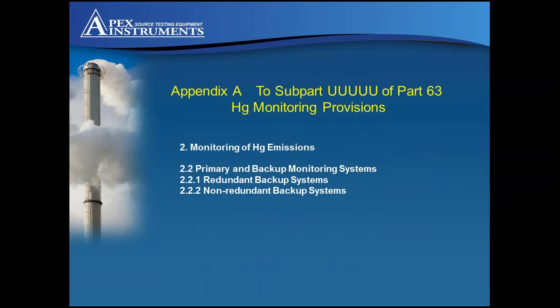So this non-redundant system is available on cold standby and can be used at the stack location for a maximum of 720 hours per year. To use a non-redundant system at that stack location for more than 720 hours, a RATA test must be performed and passed at that location.